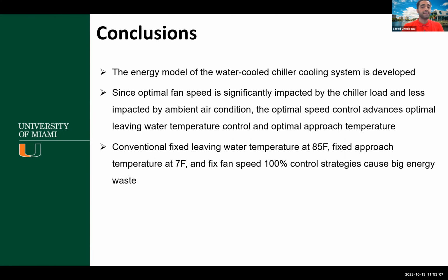Finally, in this study we developed the energy model of the water-cooled chiller cooling system. Since the optimal fan speed is significantly impacted by the chiller load and less impacted by ambient air wet bulb temperature, we can see that the optimal fan speed control is better than the optimal leaving water temperature control and the optimal approach temperature control.